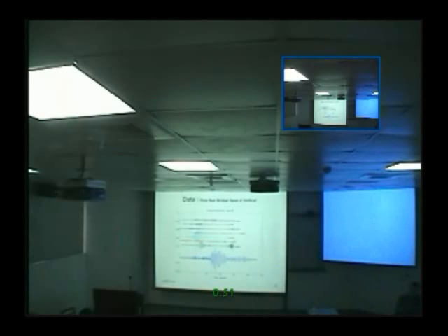Before the bridge actually collapses, it has to go through this range. That means you apply more stress and the strain will increase a lot, but it's still not breaking. And by the time you break, you get to this range. So if we have any method that can detect that the bridge gets into this range, that's the most sensitive.